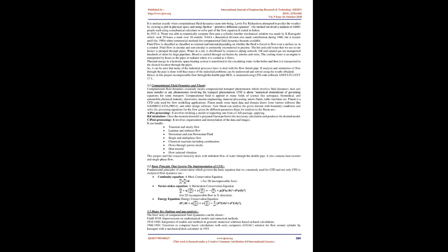In order to intensify the heat transfer from the heat exchanger surface to fluids, it is possible to increase convection coefficient by growing the fluid velocity, widen temperature difference between surface and fluids, or increase the surface area across which the convection occurs. Extended surfaces, in the form of longitudinal or radial fins, are common applications where the need to enhance the heat transfer between a surface and an adjacent fluid exists. Several researchers used extended surfaces for the enhancement in the heat transfer.